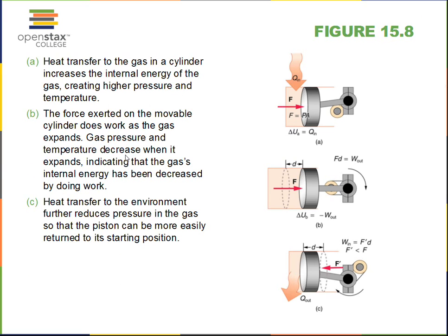So tying in some of the older concepts too regarding pressure, force, and area. When our gas system is confined to a cylinder and we have a movable piston that can go up and down, we're looking at perhaps the piston in a gasoline engine and the crankshaft down here that receives this mechanical energy. So we have Q coming in. Maybe we burn gasoline in the cylinder and we release energy here. That's going to create extra pressure in the system, and that pressure acts over an area. There'll be a force on this piston to move it.